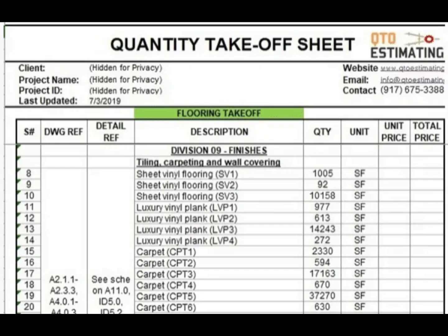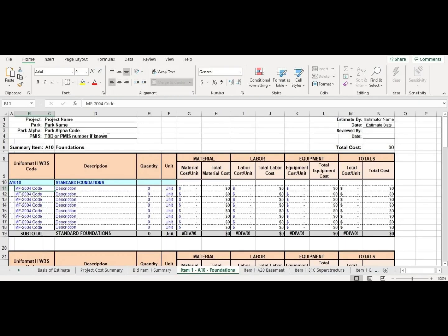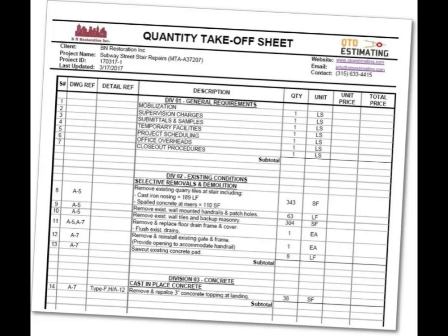Step 9. Build the final MTO table. The final takeoff should be presented in a clear table. Each row should include description, material, size, unit, quantity, drawing reference, and remarks. Use consistent terminology and material specifications. This table becomes the foundation for pricing, procurement, and construction planning.